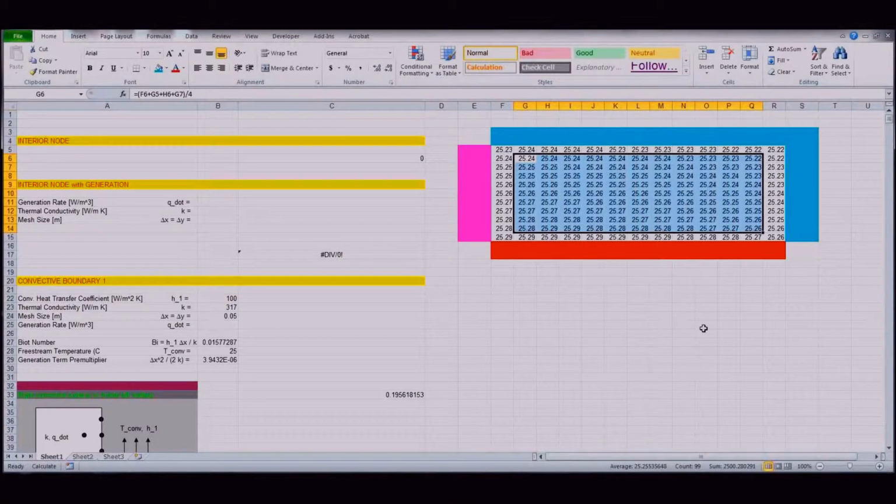So there we go, we're getting to convergence, and that's a pretty boring looking solution. The temperature going from 25.29 at the bottom to 25.23 at the top. And I wonder if this is not because we've used such a high thermal conductivity. So let's give something a try here.